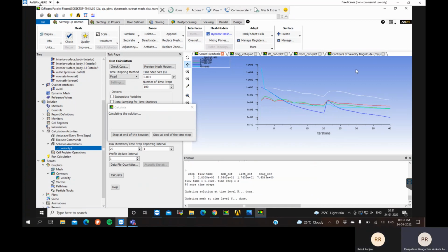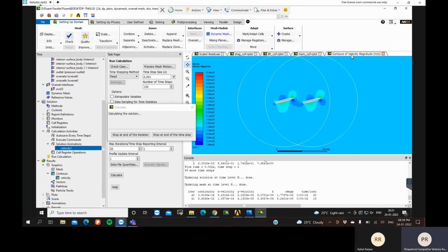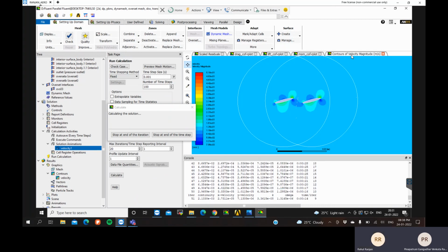While doing your mesh, you better always try to increase your orthogonality to as good as 0.3, 0.4. For structured mesh, you can sometimes get a maximum of 0.8 also. Structured mesh is always good if we want to get orthogonality, but for unstructured we cannot comment anything there.